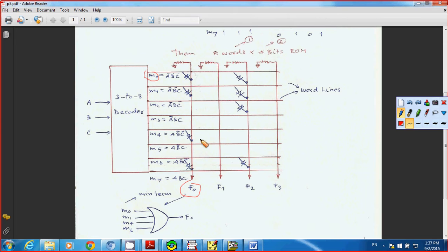Okay, this is your F0 line. And then this one is just like a diode. You connect this one to the ground, right? And if the logic becomes 1, so this one is higher than this one, so your diode is turned on. If it becomes an LED, that means your LED is on, because for the diode you need to bias this side to be positive, or the voltage has to be higher on this side, right? This is the P side.